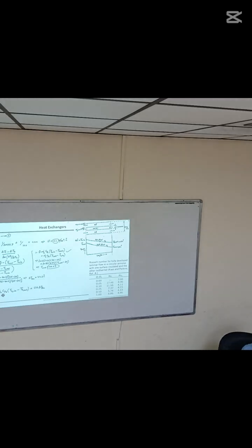And what is heat transfer? This is the heat transfer for the hot fluid, equal to UA delta T. So now the only unknown in this entire equation is the length of the pipe. U we have calculated. So this required length, now we have calculated as 70.65 meters.